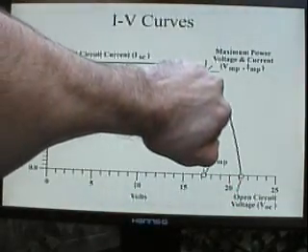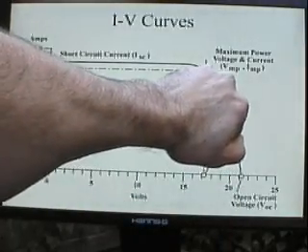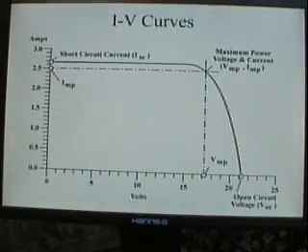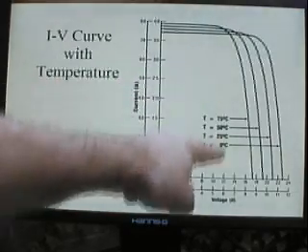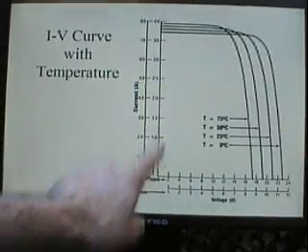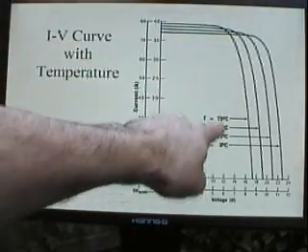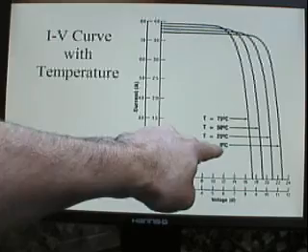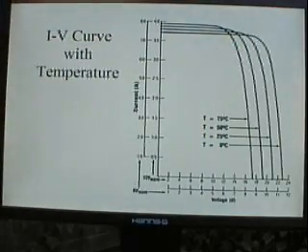And this is the max power point, where ideally the system operates right about that point on the knee of the curve. That changes with various different temperatures, and this would be for a crystal silicon. The knee is in a different place depending on different operating temperatures, so you have to adjust accordingly with balance of systems equipment. The end.